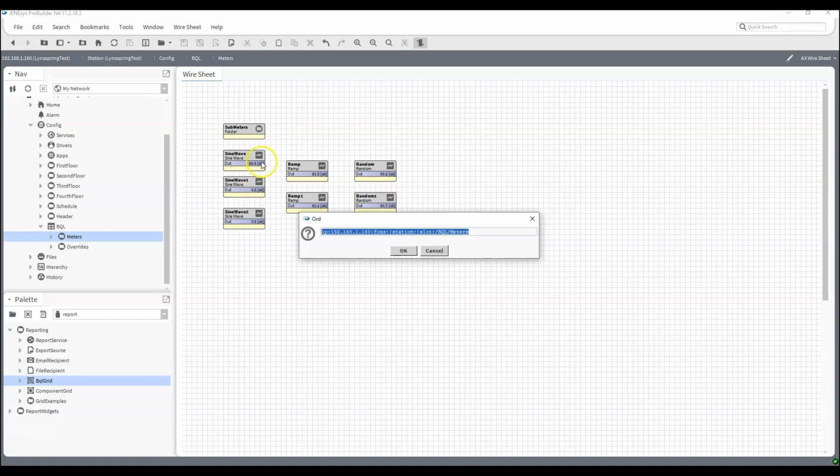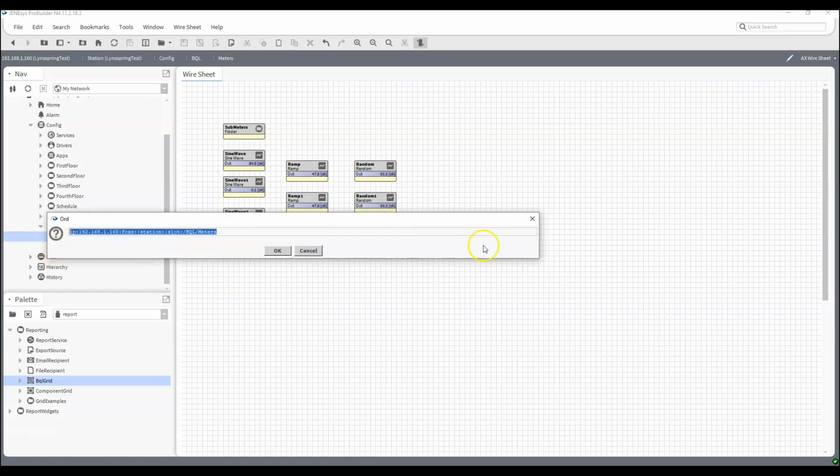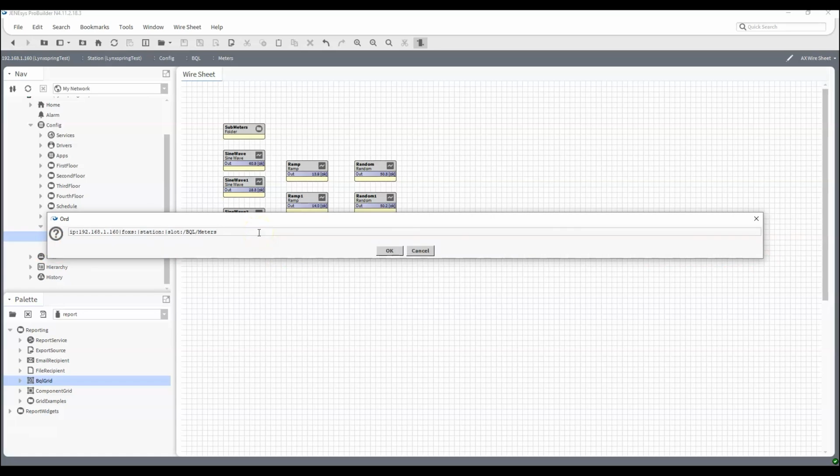So to show you that we can do things like this, again, Control L inserts the ORD that we need. And let's go with BQL select. And then we're going to use the asterisk here, from control:NumericPoint, where out.value is greater than 75.